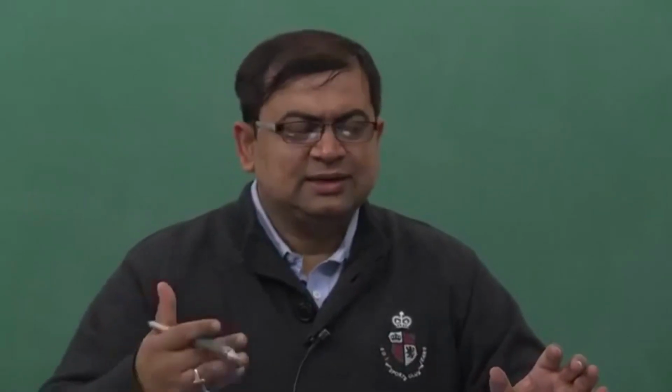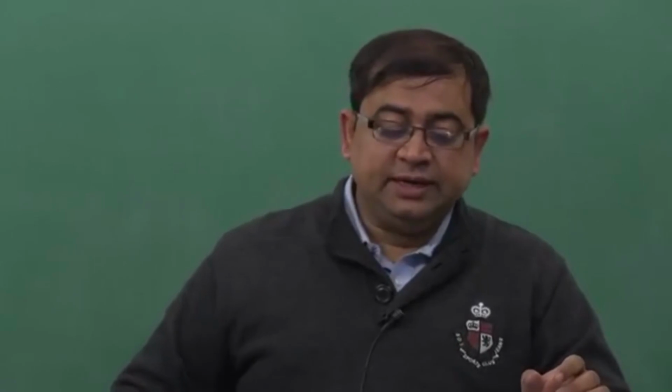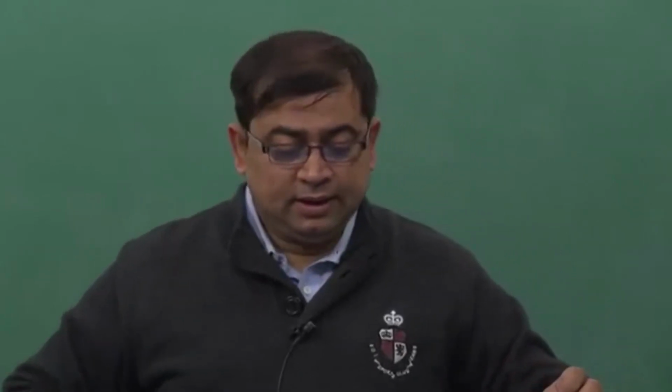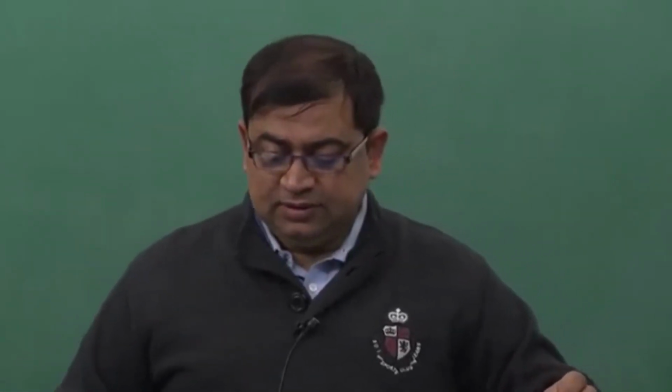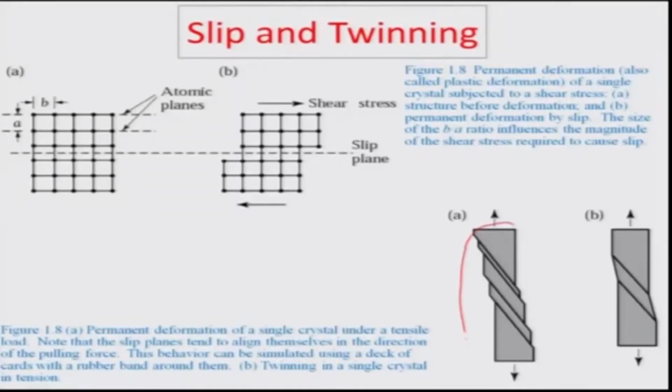Okay. So, these grain boundaries are similar to the twin planes. That is how you can probably envision it, and the difference that you can see from an external point of view is this: let us say an object is stressed longitudinally, and so the way that slip would happen would be represented here, where a permanent deformation of a single crystal under a tensile load looks like this.